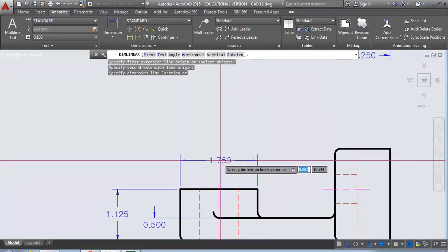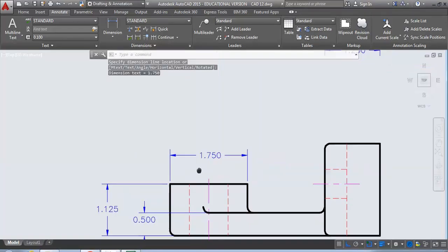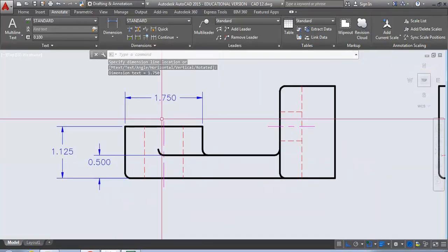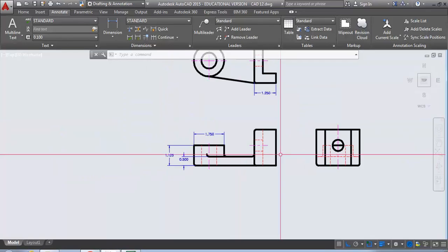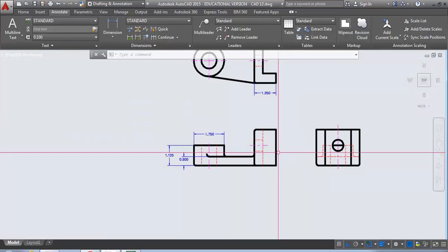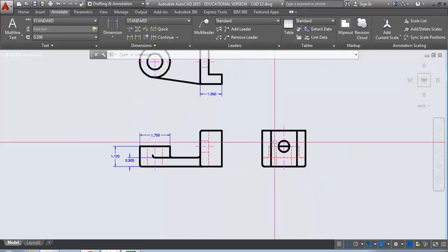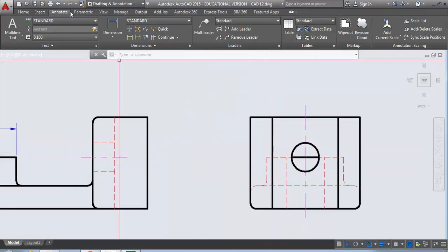It's 1 3/4. Got that. It's a good idea sometimes to check off or circle the dimensions you put on, so you know that you've put them in. Now you see where the 5/8 drill and it says M, and then it has the 7/8 M. That M means to move the dimension to the other view, so you do have the contour rule. So the dimension should be moved to this view.